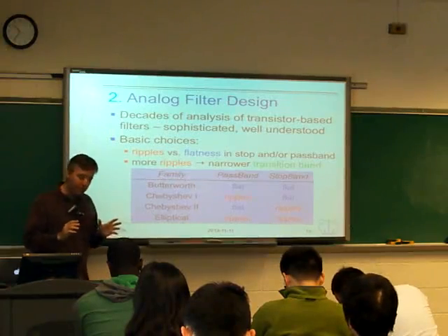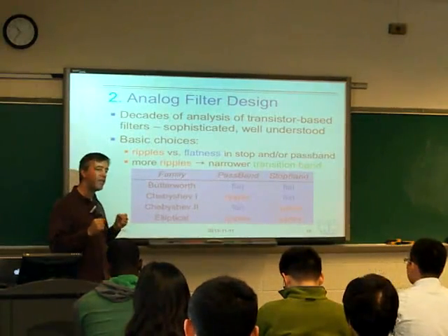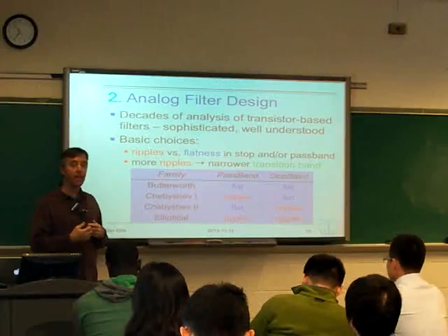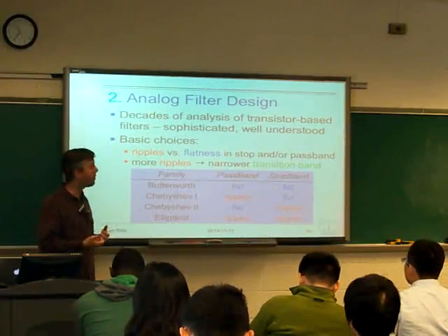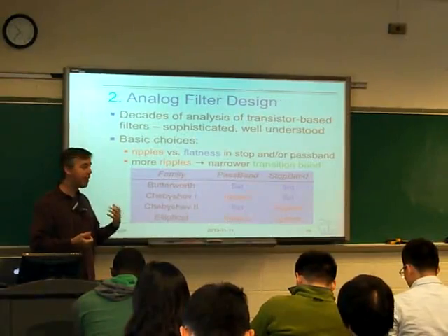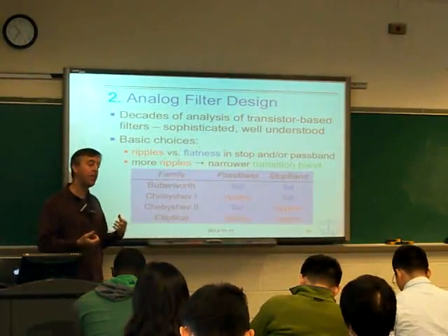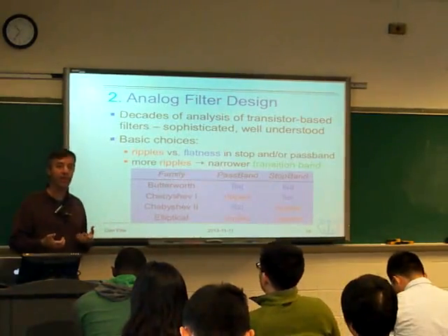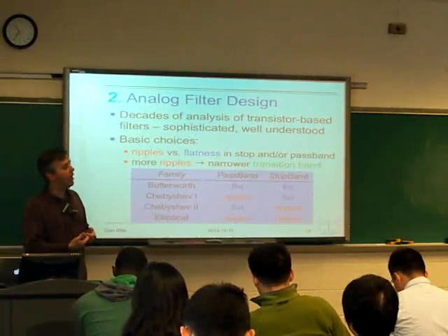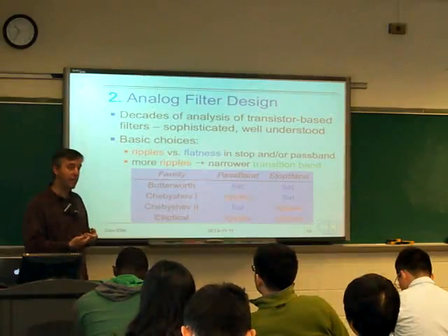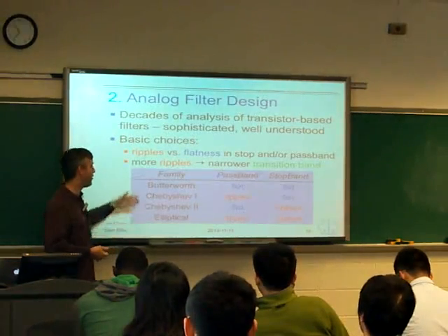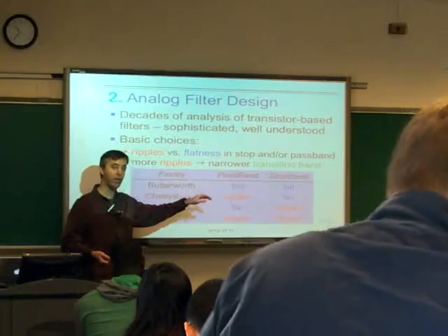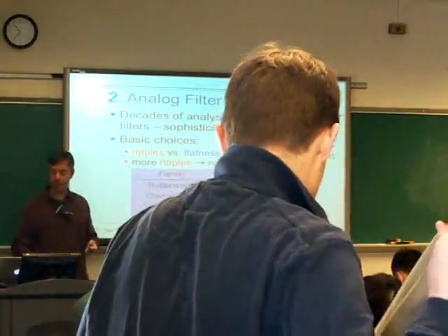Okay, so we're talking about how to design filters. We're working towards how to design IIR filters in the discrete time domain. But I've said the way we do that is actually through a transformation based on these analog continuous time domain prototypes. And so we're learning about the standard canonical ways of building analog filters, which are these 4 different classes of filter that differ in whether they are flat, meaning monotonic, or whether they have ripples in the pass band or the stop band.